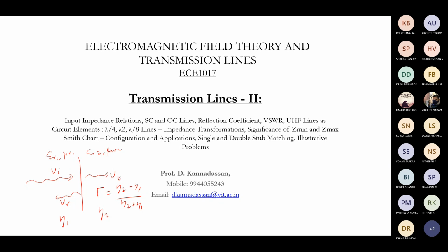That is how it can happen in real mediums. But in transmission lines, there are interesting techniques that can be adopted to make the reflection coefficient equal to 0. Then only can we say that the wave will travel from one medium to another with maximum transmission, or from one transmission line to another, and we can avoid the reflections. There are some problems with reflections that we will discuss over the course.